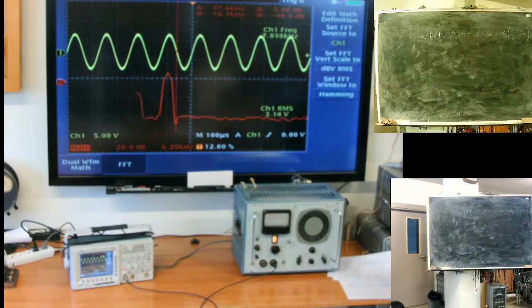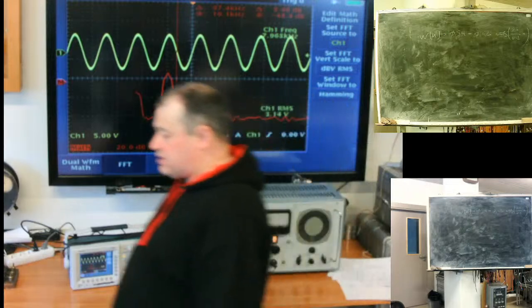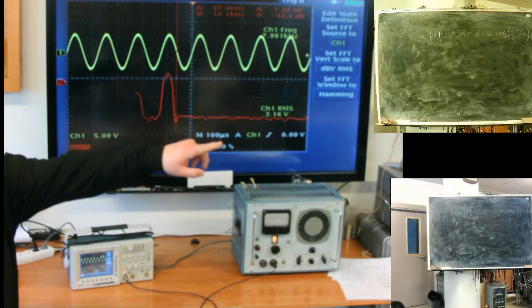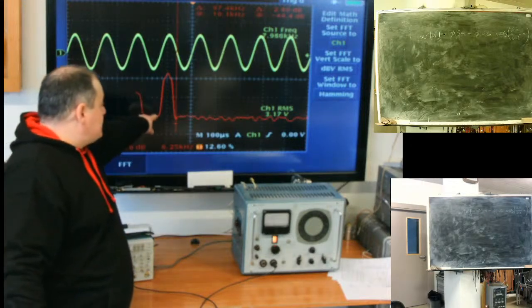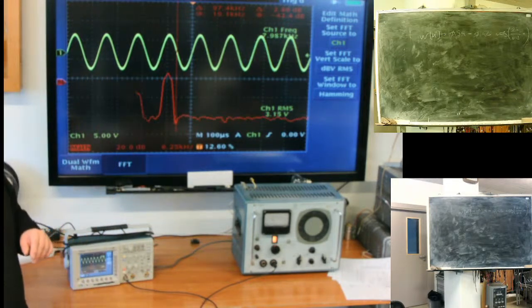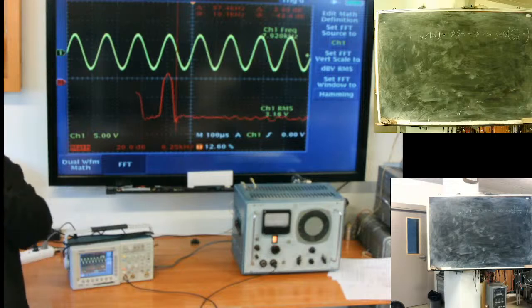Actually, switch to the Hamming window. This is the normalized line for rectangular, normalized to the peak point. For the rectangular window, it's only minus 14 decibels. Now it's below minus 40, minus 42. So applying this kind of window, I got this baseline, or its official name, central lobe, or central frequency band.